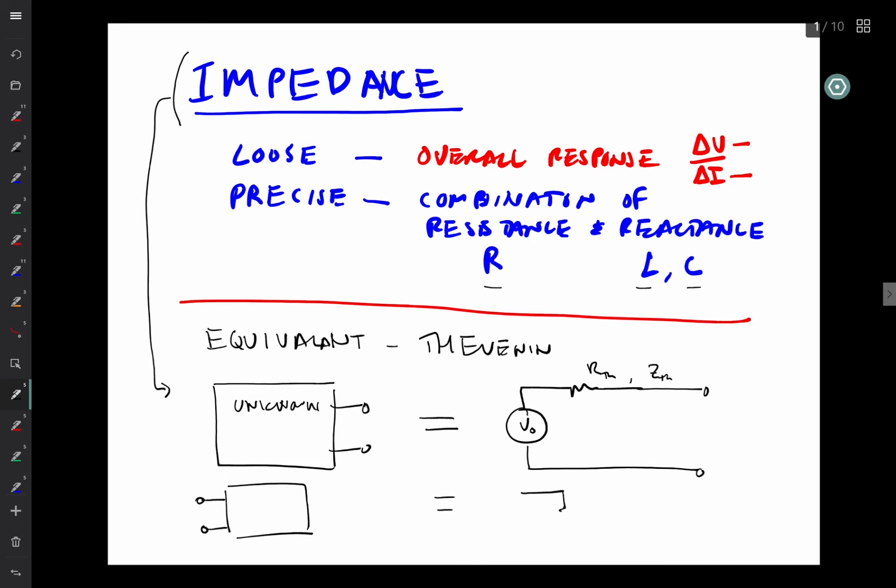But for the most part, if I think of a Thevenin equivalent of an input, usually V0 is equal to 0. That is, we don't typically have inputs of circuits that we really make that have some non-zero input voltage already on the input. It usually is applied from the output of some other device.